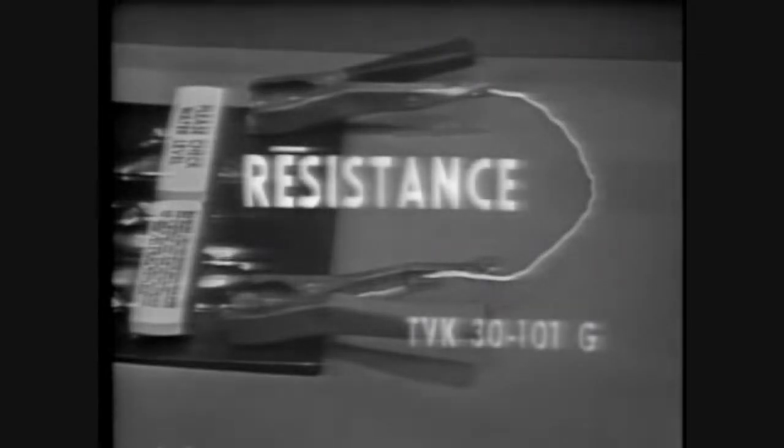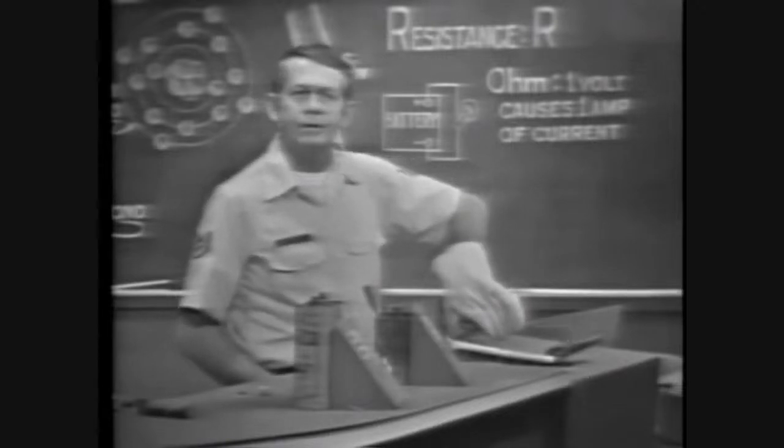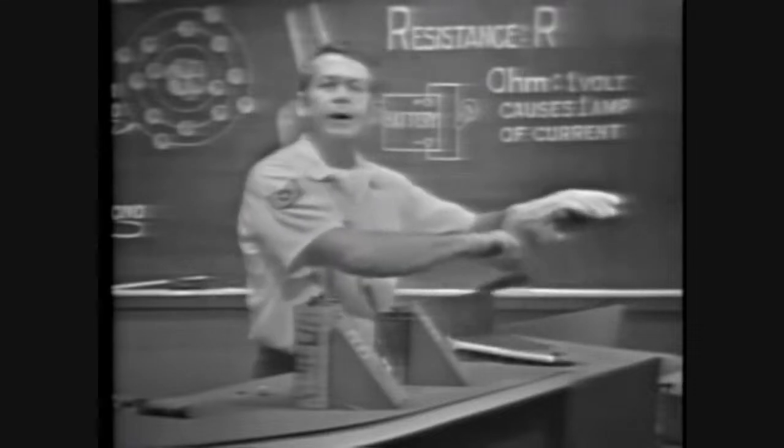Connecting this wire across the battery, it doesn't burn up. It starts to heat up until it's red hot, but it doesn't allow too much current to flow. The reason that it doesn't burn up is because this is a semiconductor material. It offers resistance to current flow, opposition to the movement of electrons. By introducing resistance into the circuit, then current can be controlled. In this lesson, we'll discuss the factors that determine resistance, and we'll talk about resistors, devices that are designed to offer specific amounts of resistance.